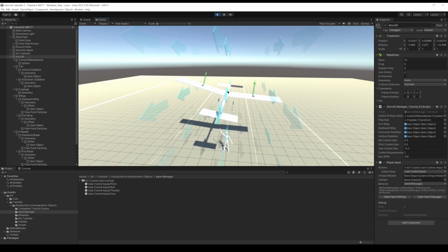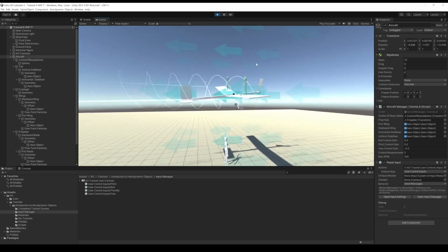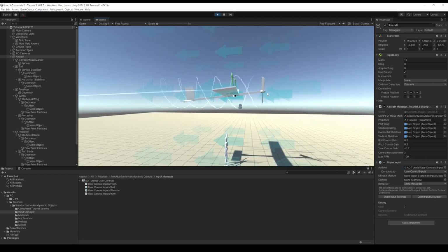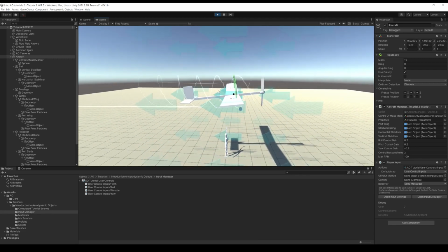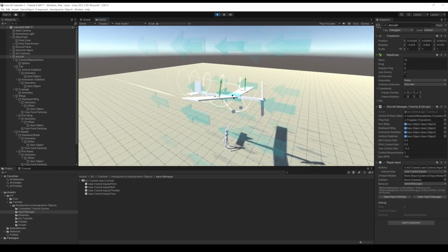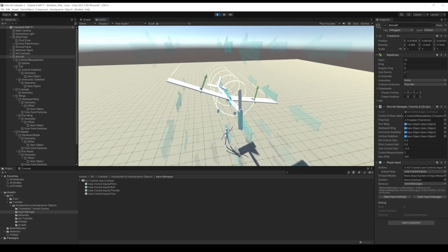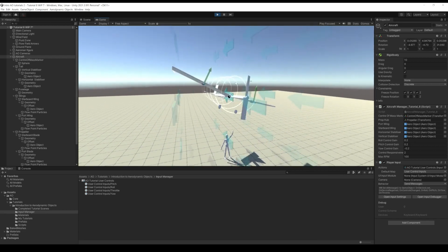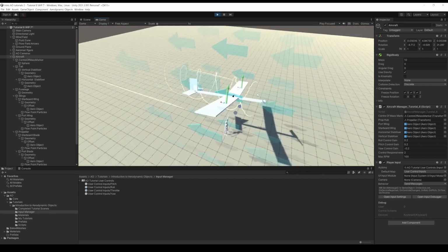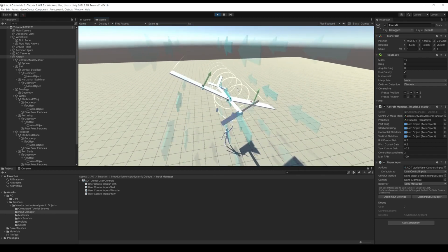We can put the throttle on at this stage. It shouldn't actually make any difference to the trim of the aircraft because we've got the thrust line aligned with the centre of gravity, so the thrust of the propeller is pretty much going straight through the centre of gravity, so there's no pitching moment from the propeller. In many aircraft configurations where the propeller is not lined exactly with the centre of gravity, when you turn the propeller on you get a change in pitch. So there's often quite a lot of work setting up the thrust line of the engine so that it has the behaviour you want. Fantastic, so we've got our aircraft flying on the gimbal satisfactorily.